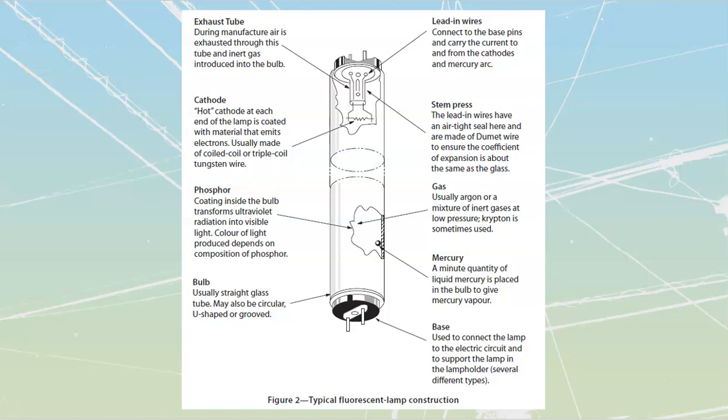So if I have a T12, that means that number 12 inside of there means that bulb has a diameter, or a distance across, that is going to be 12/8. 12/8, which we can change that fraction into 1.5 inches. So it's a 1.5 inch diameter tube.